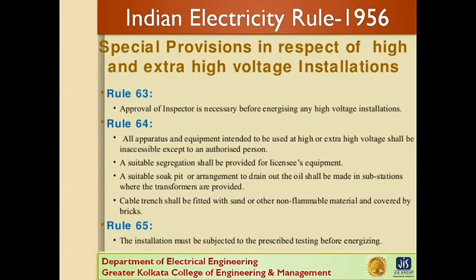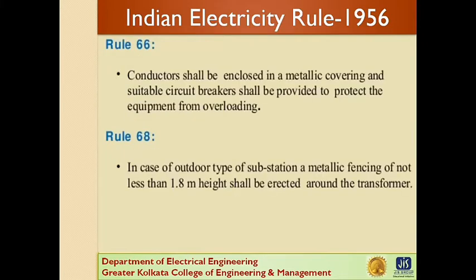A suitable soak pit or arrangement to drain out the oil shall be made in substations where the transformers are provided. Cable trenches shall be filled with sand or other non-inflammable material and covered by brick. The installation must be subjected to the prescribed testing before the energizing.